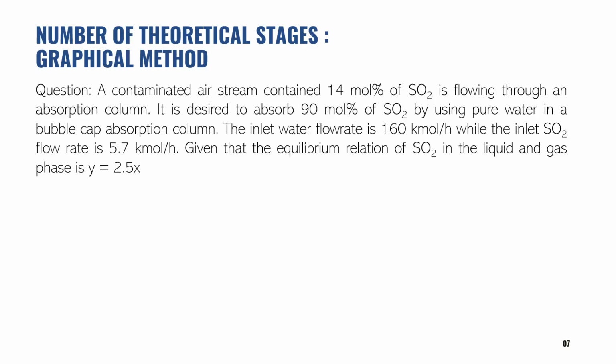Alright, so particularly for today, I am going to show you how to evaluate the number of theoretical stages for counter current in plate tower or tray tower using graphical method. Okay, let's see the question here. Example.